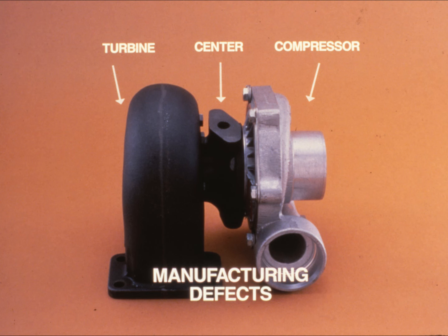The last cause of turbocharger failure, a manufacturing defect, is quite rare. As noted earlier, manufacturing defects usually cause low-hour failures. The more common manufacturing defects are undrilled oil passages and porous center housing castings. Seal failures due to improper assembly have been identified as well.